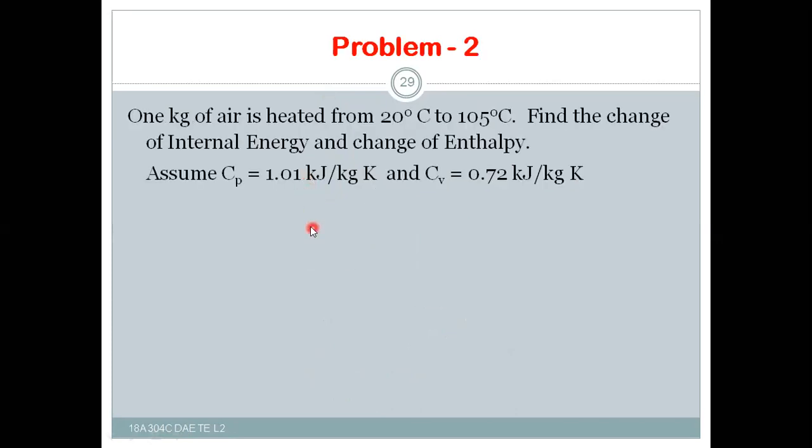So, problem number 2. 1 kg of air is heated from 20 degrees centigrade to 105 degrees centigrade. Find the change in internal energy and change in enthalpy.